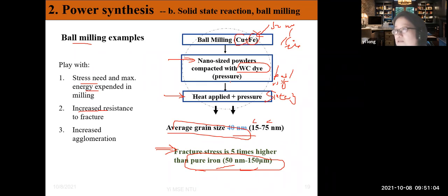So this is about process. Am I correct? You use ball milling, you reduce down the size, then you follow by sintering. Okay, so this is the process. So which part is the structure? So we said before, right, process. The big three science are ceramics, and material science is process. So the process you design is you use ball milling, then you get a very small size, then you apply heat and pressure to get your densified bulk materials.